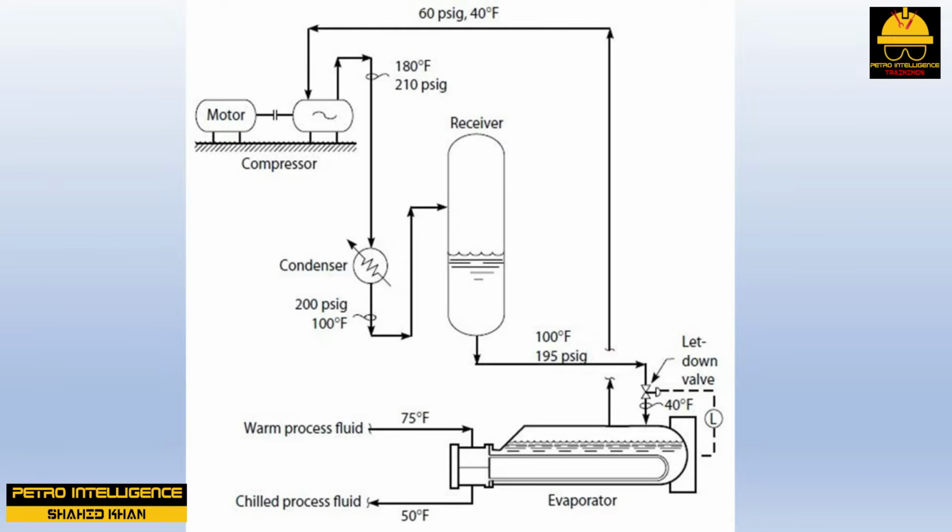Typically, 75 to 80% of the condenser heat duty is the latent heat of condensation of the refrigerant. The remaining heat duty is sensible heat removal. The sensible heat removed is a combination of desuperheating the vapor and subcooling the condensed liquid refrigerant.